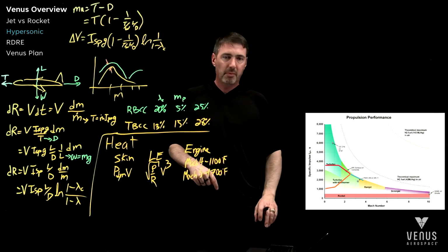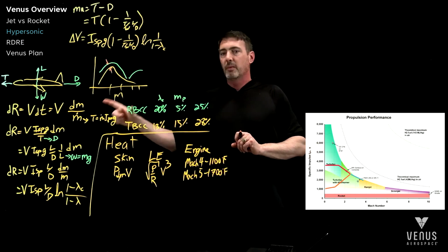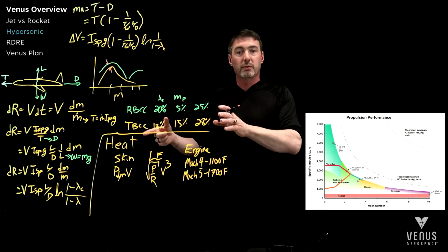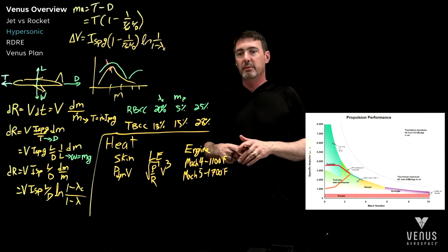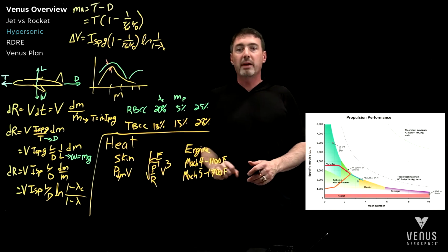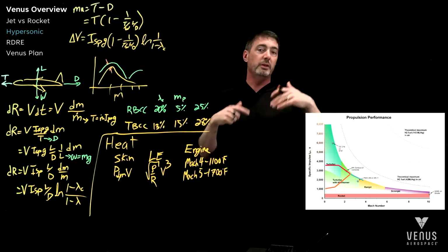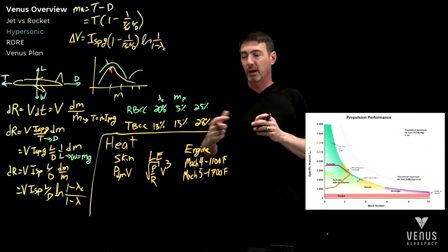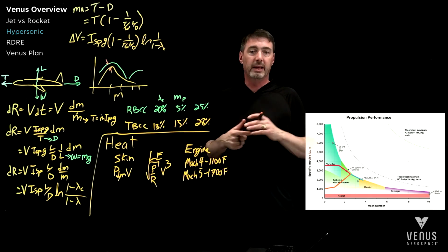Now, a couple more things on aircraft. We've talked about the range. We've talked about how much fuel to get up to that ramjet cruise operation. We've talked a little bit about the heat. Again, to get away from skin friction heat, you will want to go to a higher altitude. That's the benefit of the rocket-based combined cycle. You can then drive up to higher altitudes. Leading edges, we all have to pay attention to that. That's that fight between drag and heat reduction.